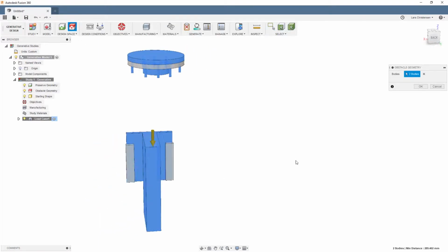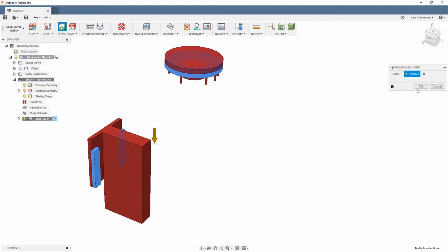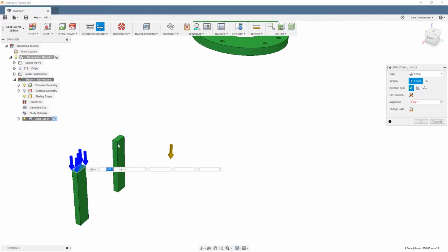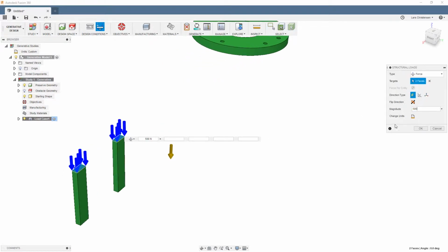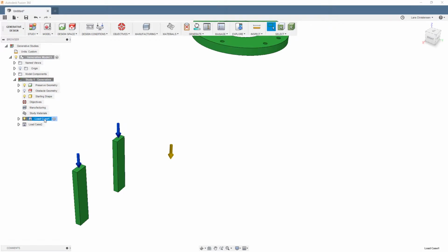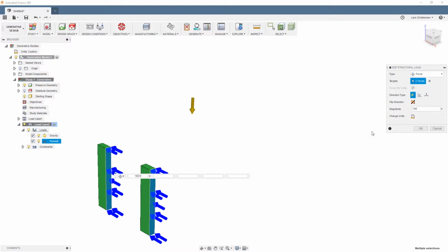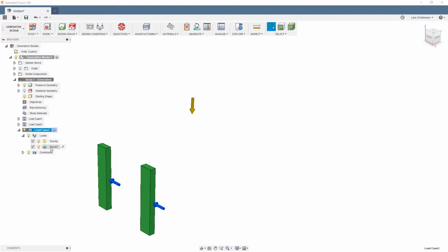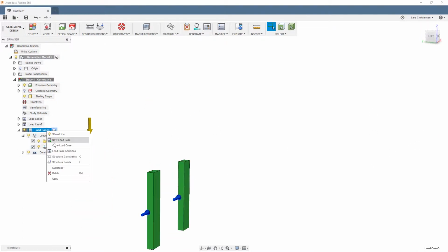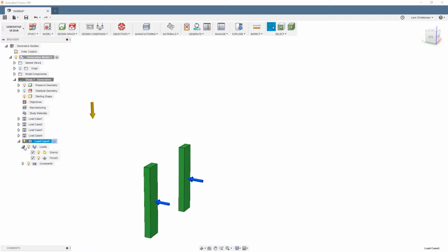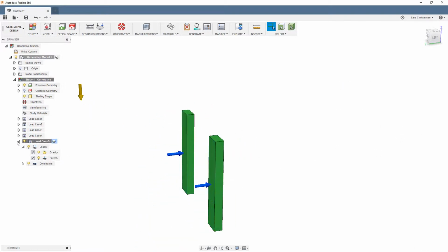With the new update in place, we can look at the Generative Design workflow. We will specify the preserve regions and the obstacle regions, apply a constraint to where the bracket will be mounted to the robot arm, and then apply the loads to the portion where the spot welder is mounted. The spot welder, now without the heavy gauge bracket, weighs about 50 kilos. And though there is no physical load in the other directions, we will apply a reaction load as the spot welder can rotate 360 degrees.